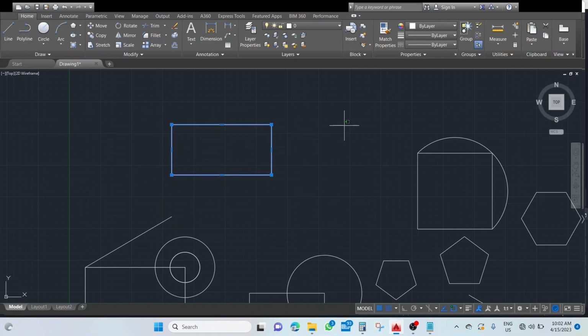So simply, to select the area in AutoCAD, left click at an appropriate position, then drag the mouse without keeping the left click pressed, just release it. Now move the cursor, select the area, and again left click. So this area gets selected.